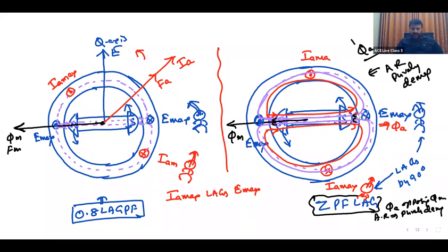Okay, sir. Okay. Rotor is rotating in counterclockwise direction. That's the reason I am saying this is cross, this is dot. Okay. Now E is maximum here. But where is the current maximum, tell me? Rotor is rotating in counterclockwise. 90 degrees lag is needed. IA maximum must lag the E maximum by 90 degrees. So where should it come? It should be here. Correct? Here the cross. Similarly, the dot of the current should also lag the dot of the voltage by 90 degrees.